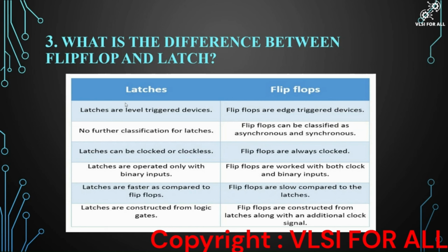It may be asynchronous or synchronous. And latches can work without clock or with clock. But flip-flops cannot work without a clock signal. They always require a clock signal. Latches are operated only with binary inputs, whereas flip-flops work with clock signals as well as binary inputs. And latches are faster compared to flip-flops. Why? Because latches require less circuitry and no clock signal, so they always give the output very fast, whereas flip-flops have more complex circuitry compared to latches, right?